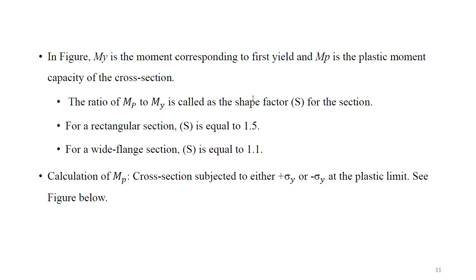The maximum compressive stress we take as sigma y and the maximum tensile stress we take as minus sigma y, at the plastic limit. The plastic limit is nothing but the maximum strain point which is going to fail, the point E, maximum yield before the breaking. The moment corresponding to that particular deformation we take as the plastic moment.